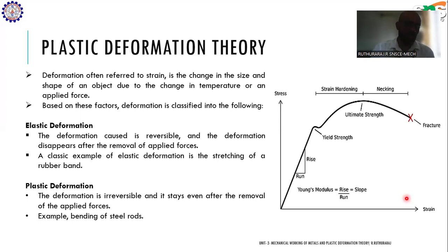Similarly, stress is also an internal force. What stress does is it prevents the deformation. So resistance to deformation, that's the actual definition for stress. The unit of stress is Newton per meter square. And strain is a ratio of change in length to the actual length. How much length is changed when you apply load compared to the original dimension. Change in dimension to the original dimension, that is called strain.